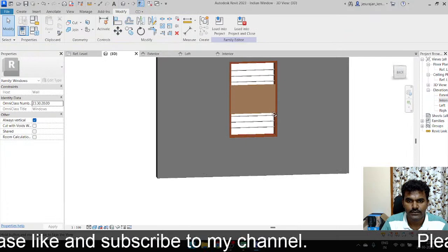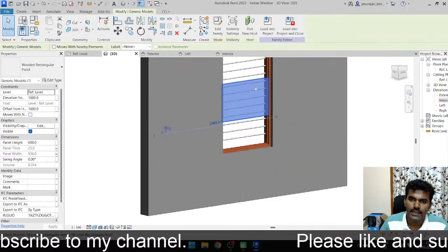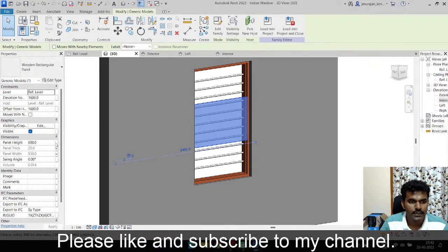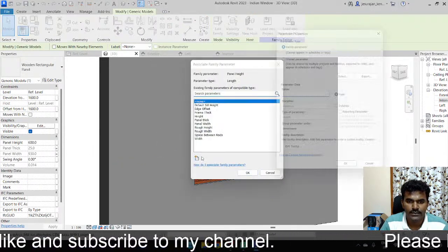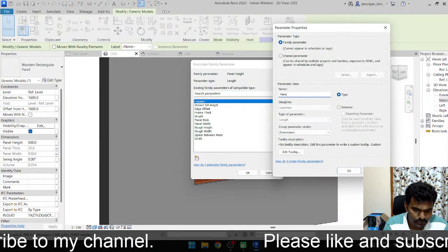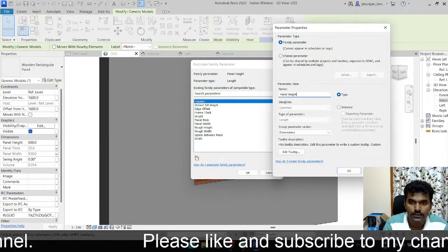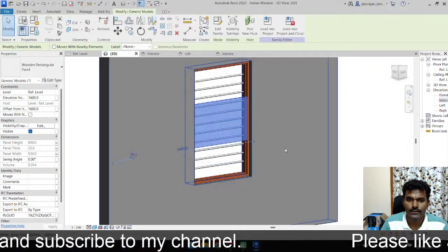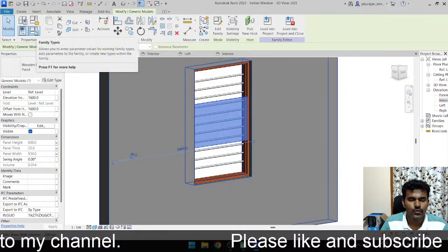Go to 3D. Panel height. Select panel height. Create a parameter. Panel height. Keep this as instance. Okay. What's the panel height?